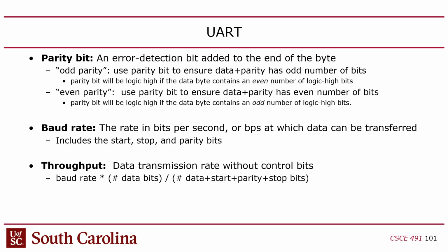If you have a parity bit, it comes right after the last data bit. It's a little confusing because you can have even parity or odd parity. Even parity refers to, parity is like the number of ones.